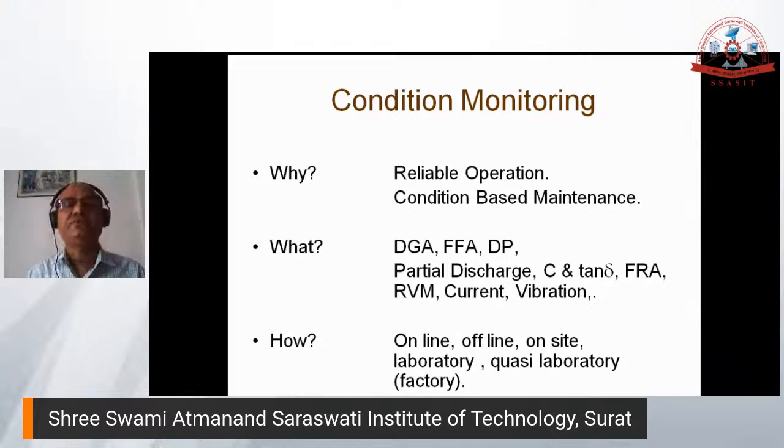Today if you do maintenance on one equipment, it will have a tag card, and after 6 months or 1 year, whatever the time schedule, the maintenance will be done based on that. But we don't check whether after 1 year it is really needed, or whether something should be done before that. That's why, instead of time based maintenance, condition monitoring is used for condition based maintenance.